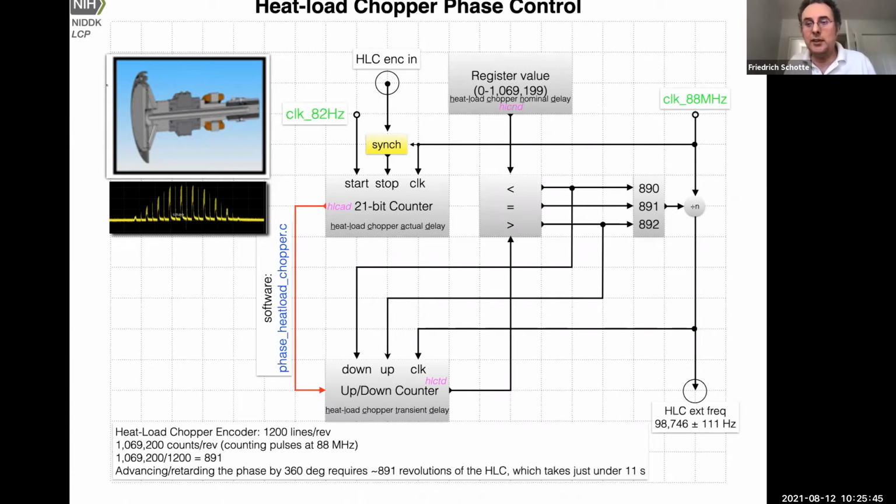So it's quite demanding to phase it because you need to maintain the frequency exactly, but you can only do very small phase shift increments. Otherwise, it loses phase lock. We do this by modulating the encoder frequency in increments of 0.1%. So this way we can slowly rotate the phase and lock it into a new phase, the phaser.